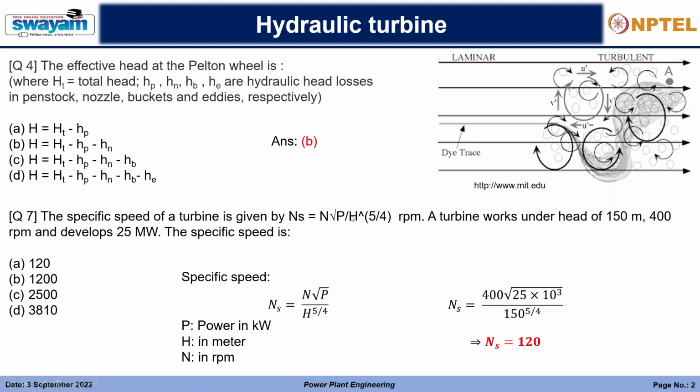Yeah, Mr. Kanwar. Yes, sir. Actually, regarding eddies, they are nothing but a circular motion of water only, right? Right, sir. So why should there exist a loss in eddies? Because you see that circular currents are being formed, and these circular currents are generally formed after the wake, that is, after striking.